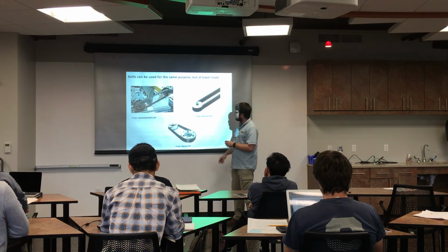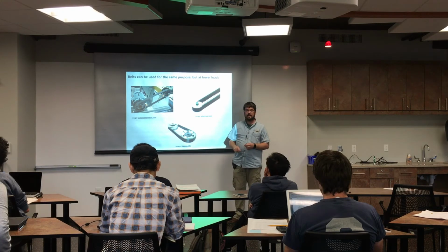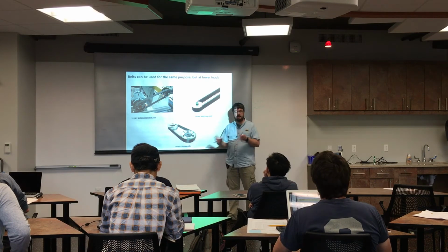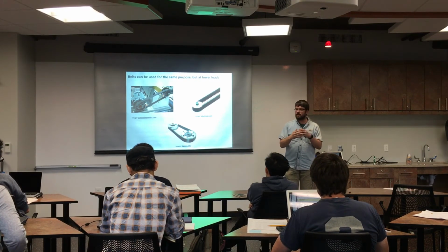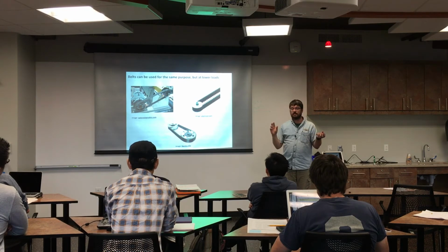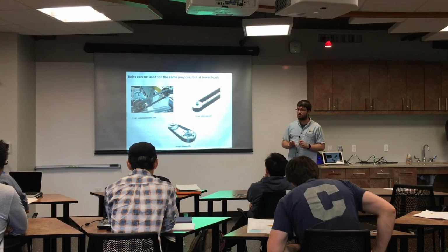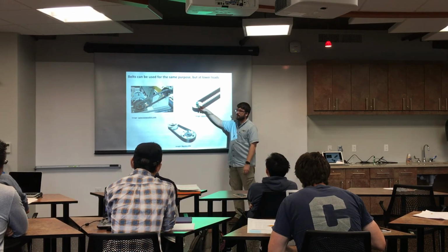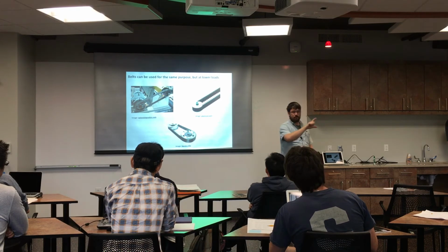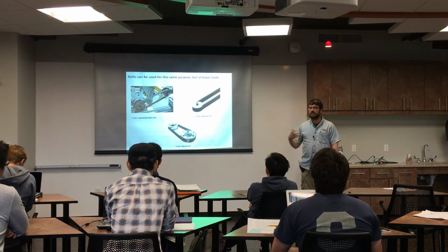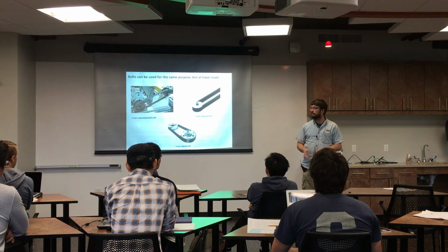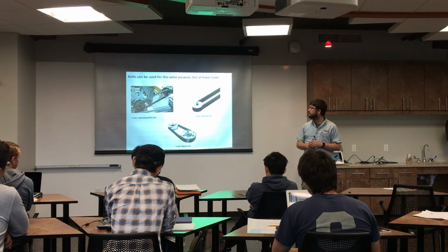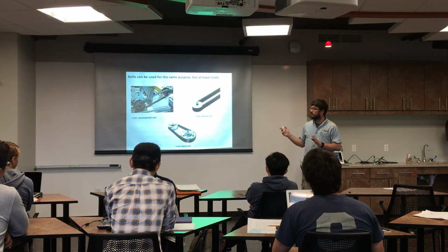But one of the things I think is most useful are these notched belts, kind of like timing belts. So you have these pulleys or cogs that have teeth on them that mesh with the teeth molded into the belt, and you can do very precise positioning with this, or relatively precise positioning. I'm not going to say very precise after we just saw the Flexure video. But this is how 3D printers are positioned. This is how the print head in your printer scans back and forth. That's how scanners move the scanning bar, all that stuff. So if you need these belts and pulleys, you can generally salvage them out of printers pretty easily. Does that make sense to everybody?